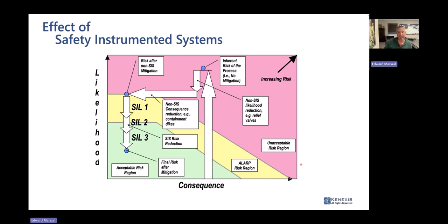This is true. Absolutely. It's all a matter of perspective, and more importantly, it's a matter of what your vent and disposal system looks like. If you have a relief valve that's discharging to atmosphere, you've basically moved where your consequence is located. So instead of your consequence being a rupture of your vessel and a major release, you're going to have a smaller release at a known location, but you can still have a consequence associated with it.